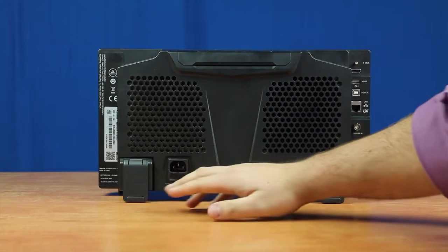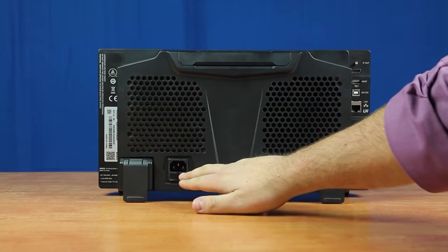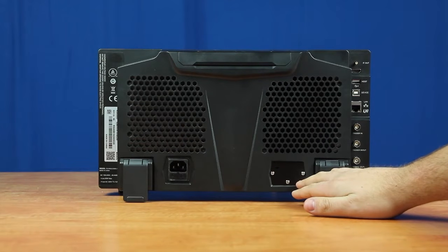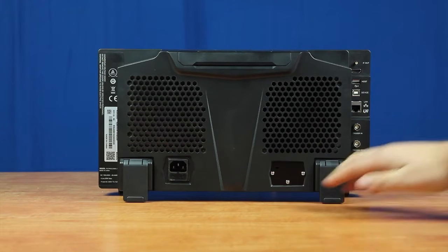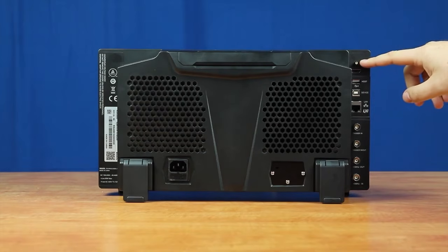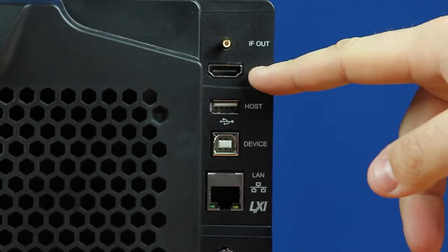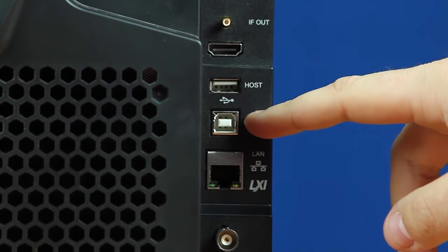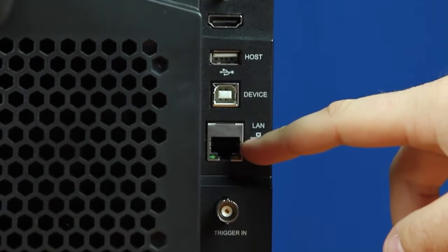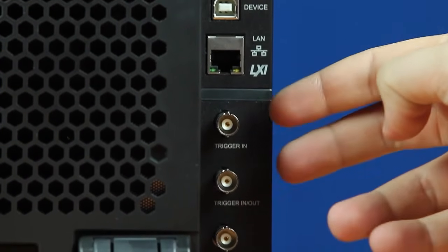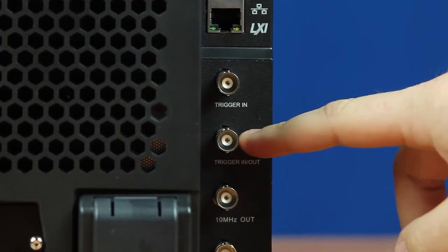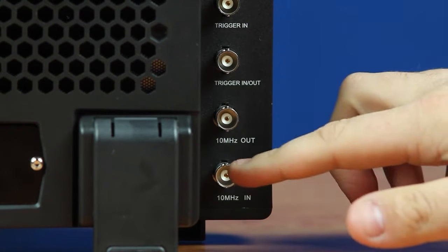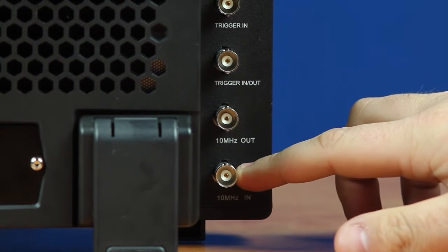On the back of the instrument, we'll find the serial number along with the power port and fuse cover. Then we can find the cover for where you can actually add an optional higher accuracy clock at any time. And right here we have our IF SMA connector, the HDMI port. Then we've got another USB host along with our USB connector, so you can control the instrument with your computer. Our LAN port, then 2 trigger ins, and this one can also be a trigger out. Our 10 megahertz out, in case you wanted the reference, and then a 10 megahertz in for a laboratory 10